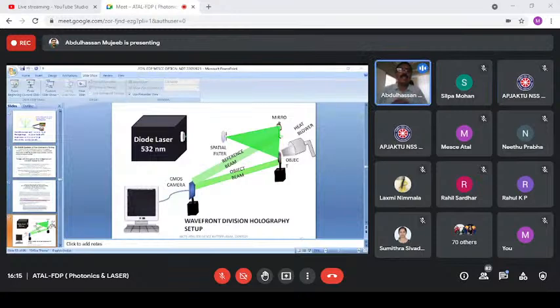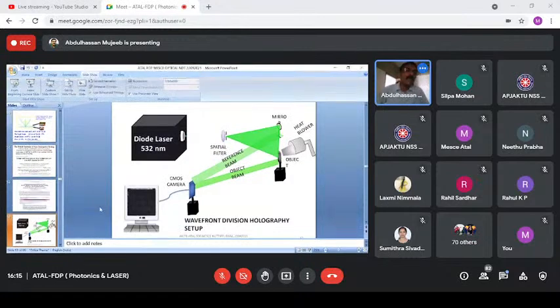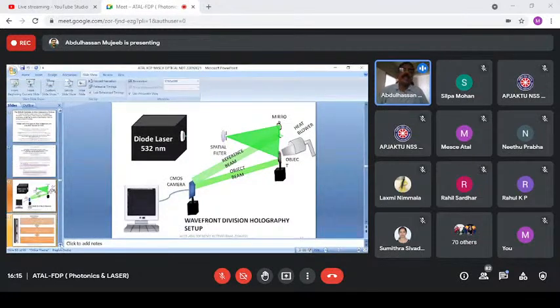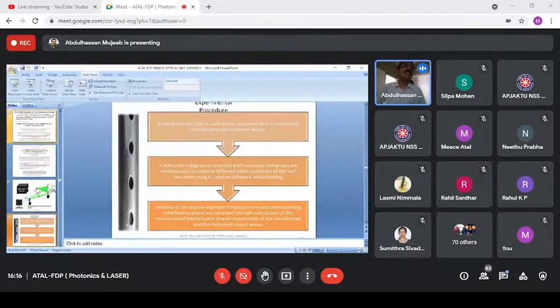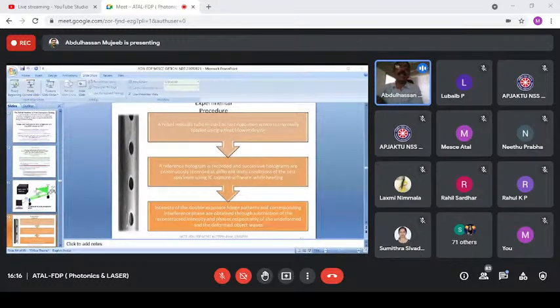After this, what we are getting is the object fringe pattern. There is a fringe pattern on the laptop. This fringe pattern will give you the recording of the hologram. So remember, this recording of a hologram is not as simple as I have shown you. The minute loading is very sensitive, for which we require a vibration isolation table. The vibration isolation table is very important. It should not capture the vibrations in and around.